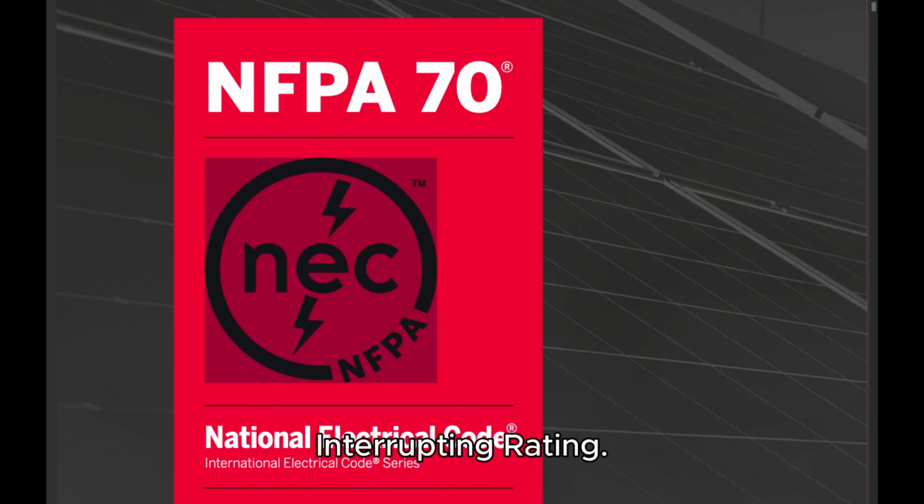110.9 Interrupting Rating. Equipment intended to interrupt current at fault levels shall have an interrupting rating at nominal circuit voltage at least equal to the current that is available at the line terminals of the equipment. Equipment intended to interrupt current at other than fault levels shall have an interrupting rating at nominal circuit voltage at least equal to the current that must be interrupted. 110.10 Circuit Impedance, Short-Circuit Current Ratings, and Other Characteristics.